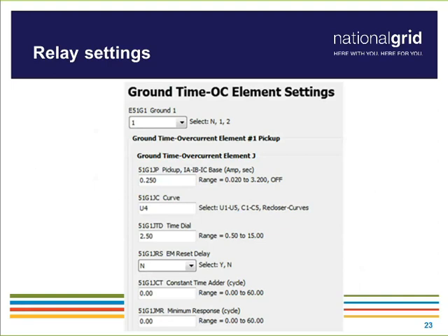So if you have ground overcurrent settings, or other fault settings required because you are using a recloser or some kind of three-phase automated device, such as a circuit breaker or some other type of automated device, we would have to review your settings to make sure they coordinate with our system. That's a requirement before we could advance to witness testing, to make sure the settings are agreeable up front and we can make any tweaks before equipment gets installed in the field in case there has to be some modification or change. This specific type of setting would only apply to those types of three-phase automated devices.